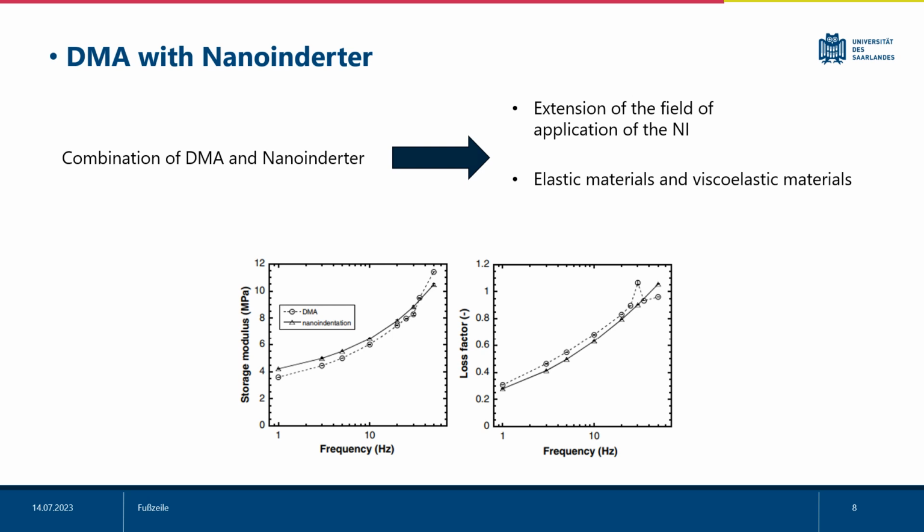Viscoelasticity can be studied using DMA during nanoindentation. By applying controlled oscillatory stress, the resulting strain can easily be measured. An elastic material will have stress and strain in phase, while a viscoelastic material will have strain lagging stress. In many applications during quality control and R&D, it's important to reliably test this behavior. We can see from this diagram the complex modulus as a function of frequency, determined by dynamic nanoindentation and